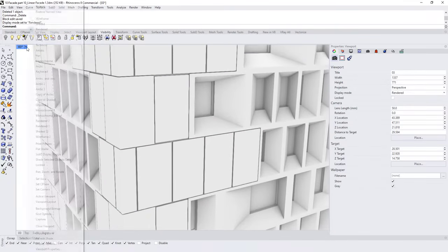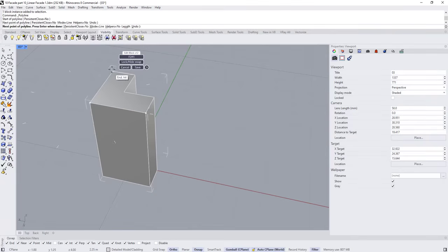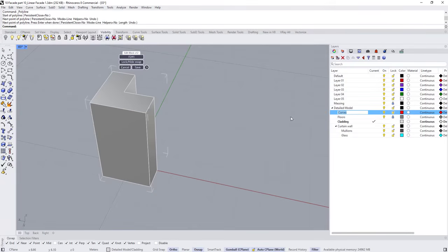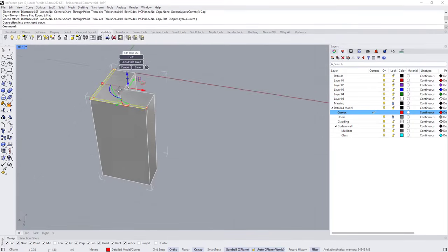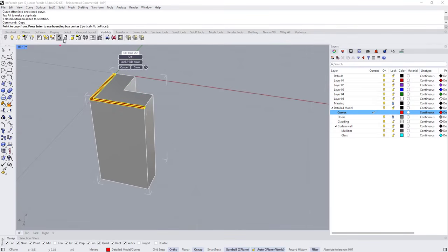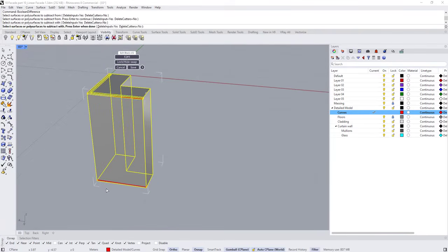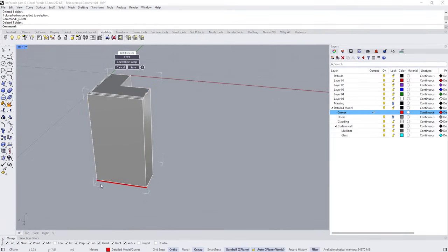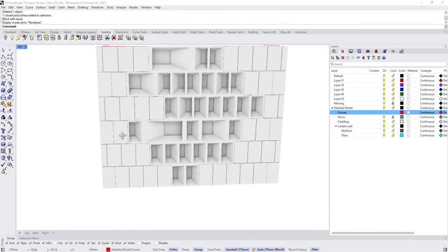I want to do the same for this one. So double click. I think there is an easier approach, but first I'm going to select the layer of the curve, because when its color is red, it's more clear. Select this and create offset 0.1 and make it flat, and extrude it down by 0.05. And move, create a copy, vertical, here, boolean difference, and let's delete the object. It's okay. Okay, yeah, this looks good.